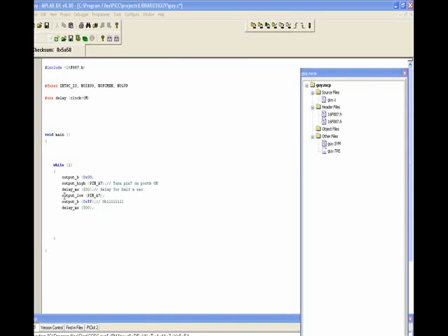Then you come to this place, you output low the pin 7. That means it was on, delayed. Now I'm going to turn it off and turn this one, which was off, on. Now, as I was saying, this is hexadecimal and it's the same thing in binary. This one tells you that all the lines on port B, because port B has 8 lines, which is an 8-bit port. Now I've turned all the bits on that port on, which is 1111. That's exactly what this is doing.